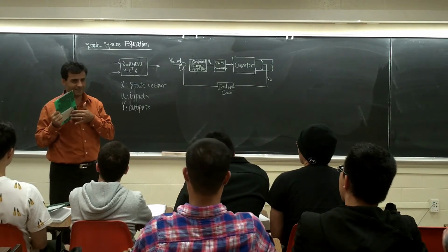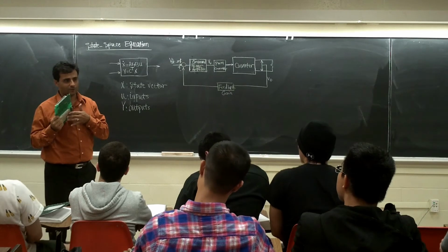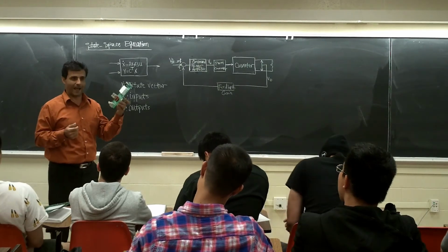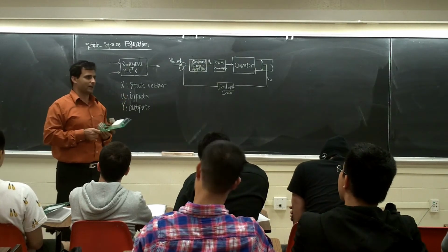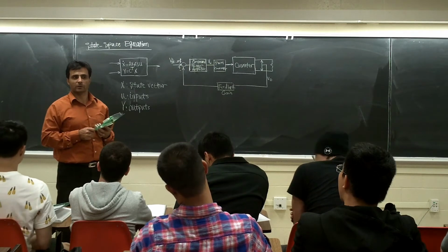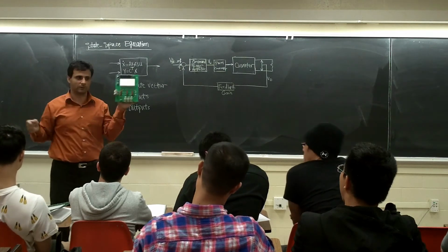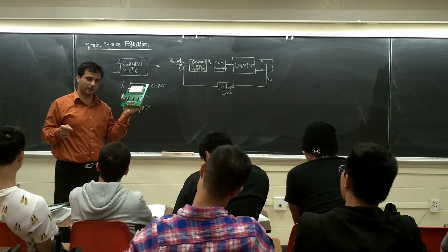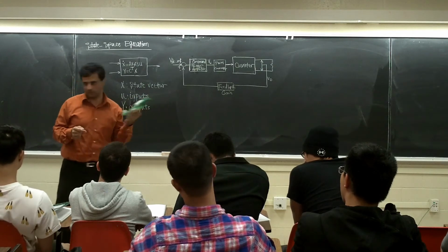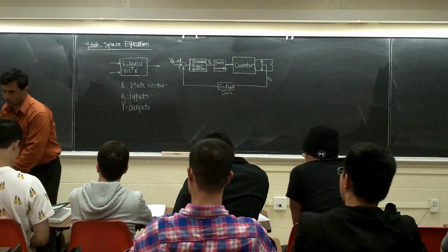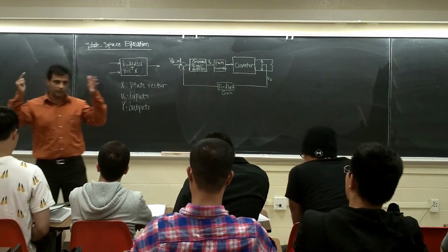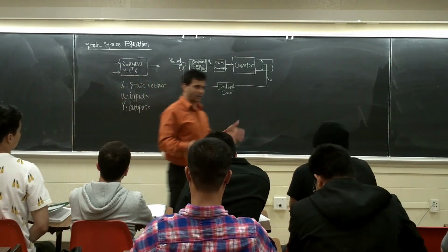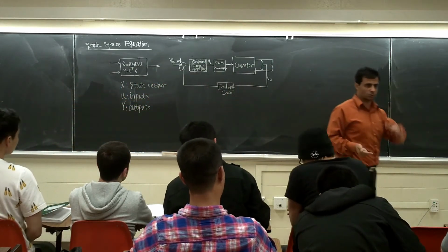But if I have a bad design, right? So let's say I said I'm going to use it for 40 amps. Now I have a 150% overshoot. So this one is going to go to more than 100 amps. Boom. This one is going to blow off, right? So these are the design. When you design this thing, you should consider all these things in the equation. You know what is going to happen if I have this much overshoot.